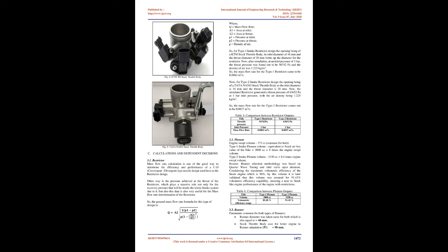to achieve it. So, in Type 1 intake, to keep things simple and to overcome cost and assembly problems, a modified version of the stock throttle body was used, where the modification was removal and sealing of the idle motor and shutting the TMAP sensor hole. So it's just a simple throttle body with only TPS output.